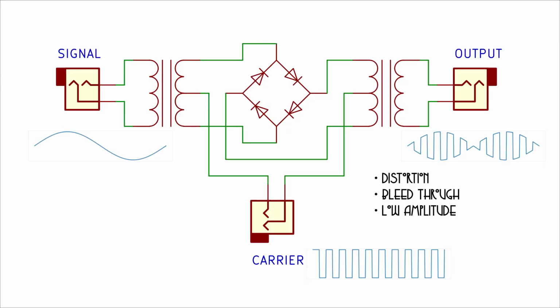But some people still like ring modulators. They've got a certain character to them. The more modern replacement circuits for them don't give you exactly the same kinds of outputs as ring modulators do. So some people still build plain old ring modulators. Ken Stone, who designs modules under the CGS name, has a design for what he calls the real ring modulator, which is 2 transformers and 4 diodes.